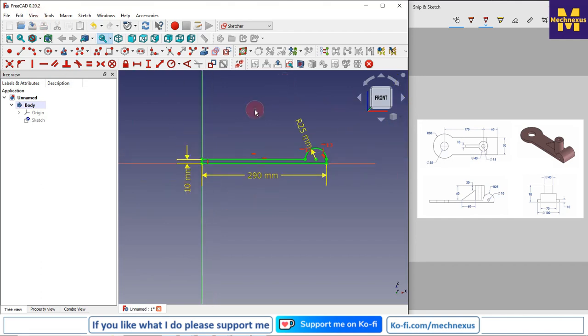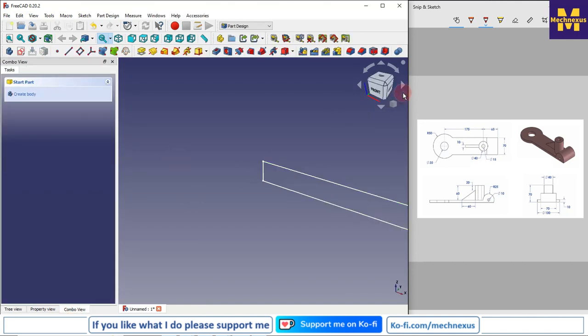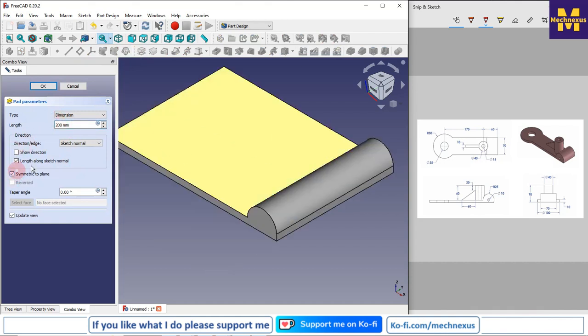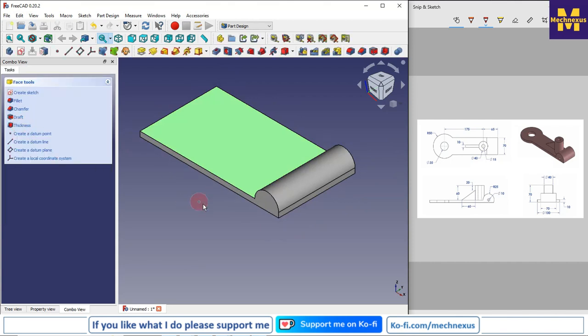I will exit the sketch, I will set the isometric view, and now I would extrude it more than 100 mm. So I will keep 200 here, and I will say symmetric to the plane, or I can say it 160. Okay.